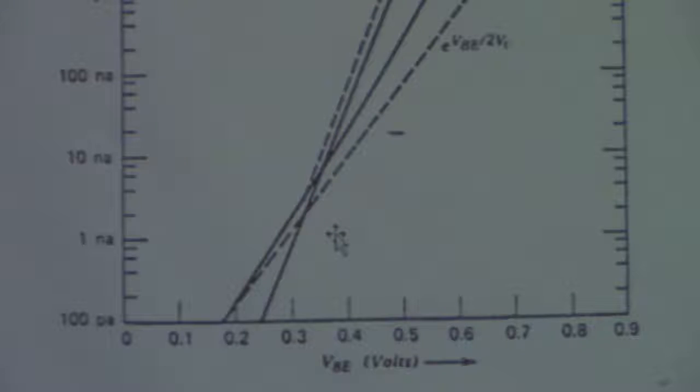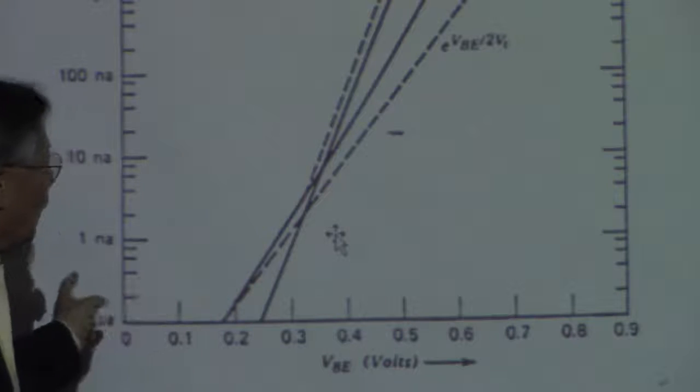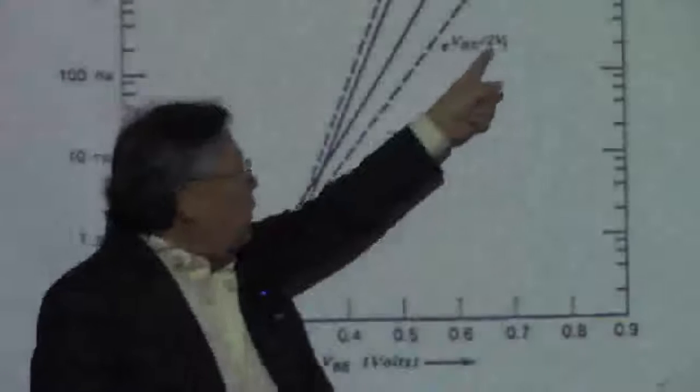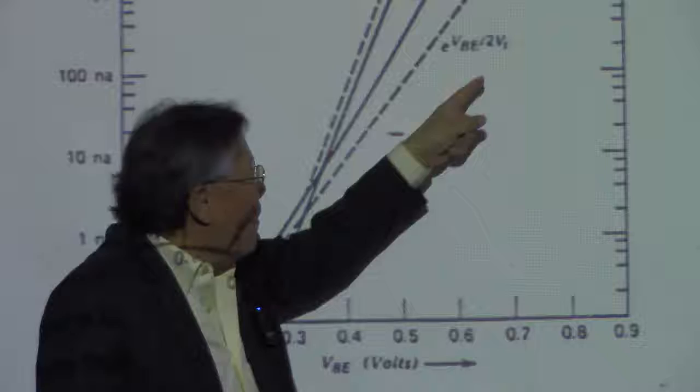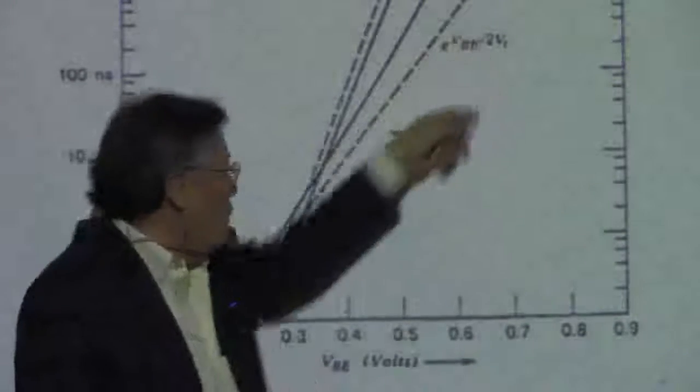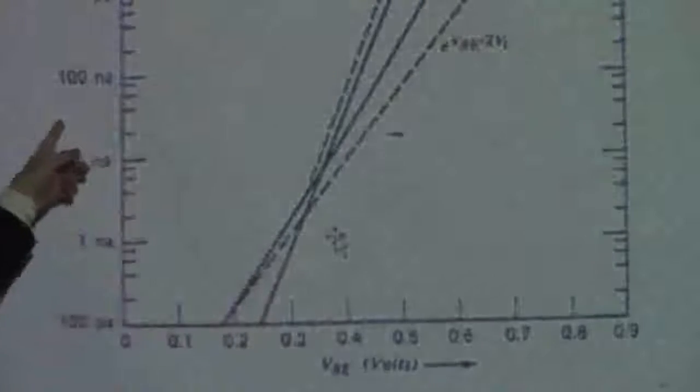You can see, at high voltages between the emitter and base, the space charge region recombination, which has been discussed in section 3, is not important. But as you get low level injections, low level voltages between emitter and base, because of this 2, if you get this small, then it's going to be important, determining the current.